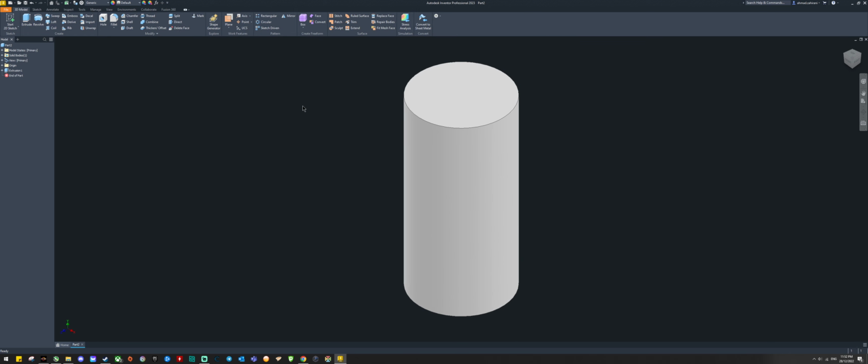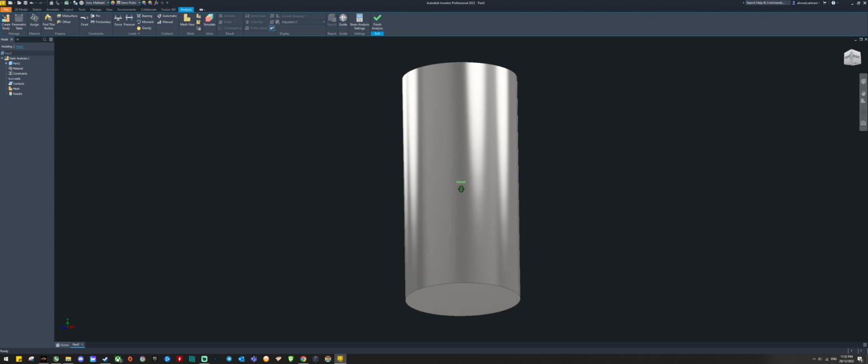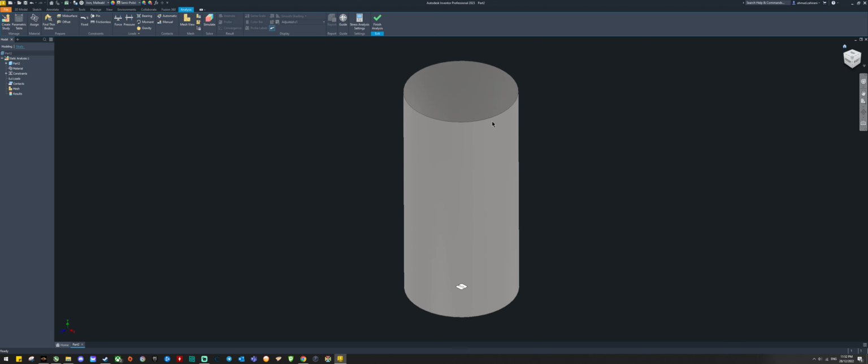Now I want to do tensile. So select stress analysis, select create study and select OK. The one material that we use right now is just iron. So check the bottom of the component and select fix for the constraint and select OK. Return to original view and then select the force and select this area, and this one we want to change the value to negative 1000 Newton. I think it cannot recognize 1000.